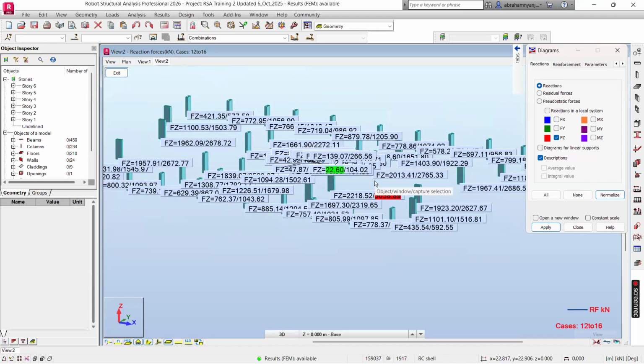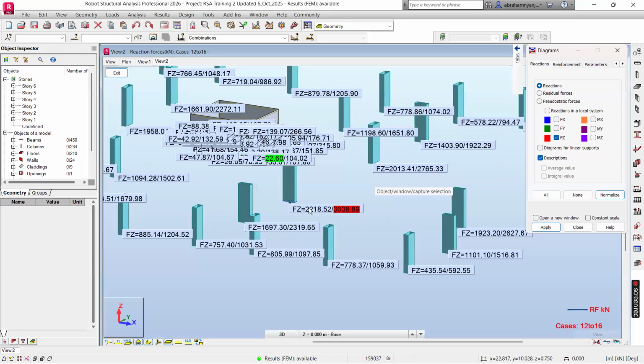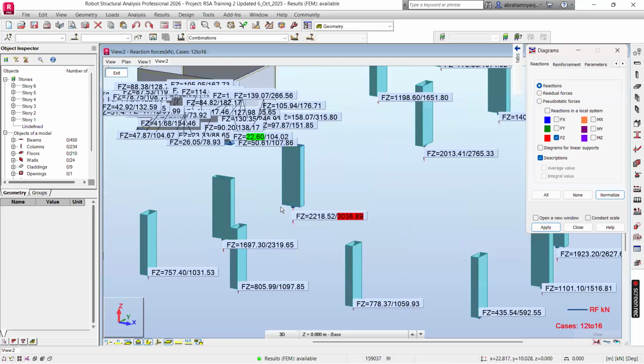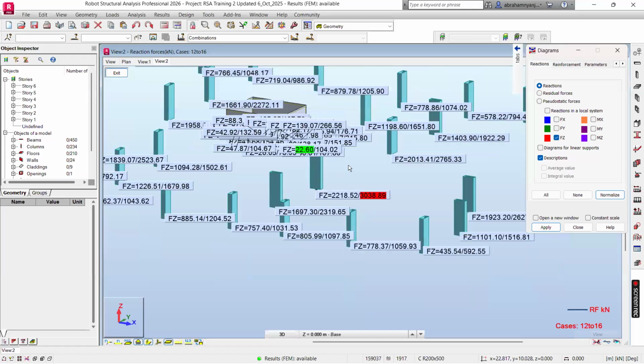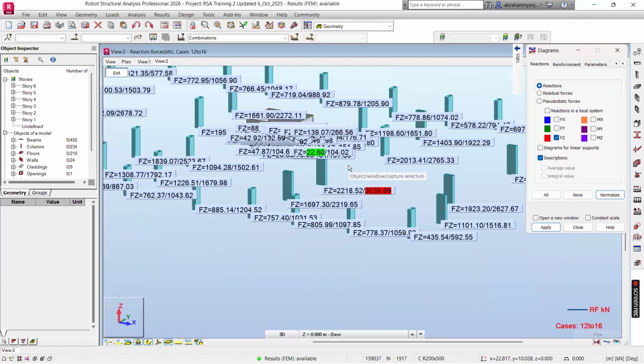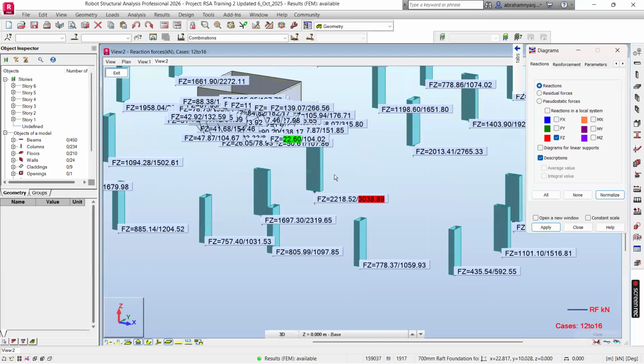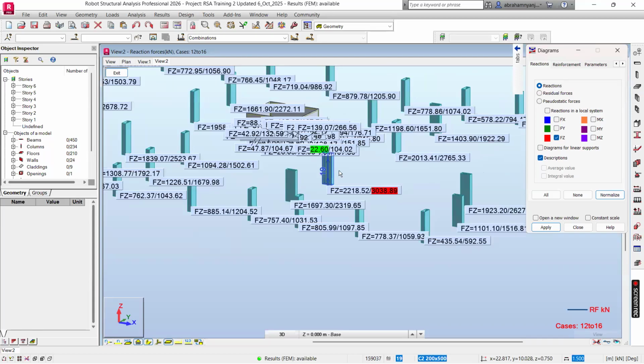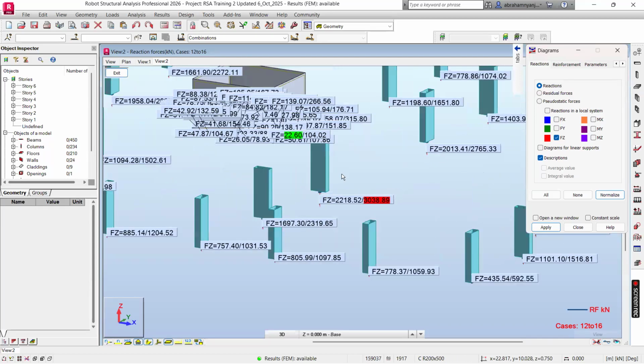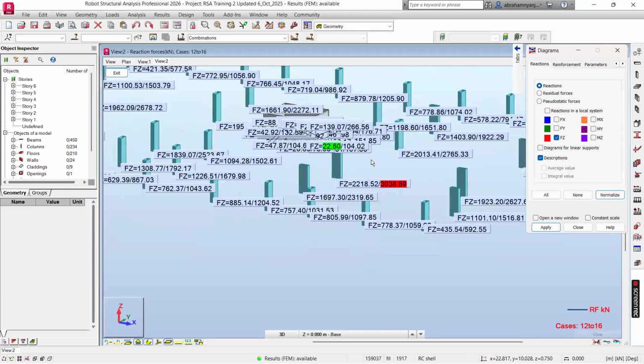You can group them depending on the bearing capacity, because this column that has the maximum might actually have the greatest bearing capacity, and the more the bearing capacity, meaning your soil can withstand load, your footing will have slightly smaller dimensions compared to a location that has lower bearing capacity, because, as we are going to see, whatever loads are applied on the footing have to be distributed onto the soil underneath your column.